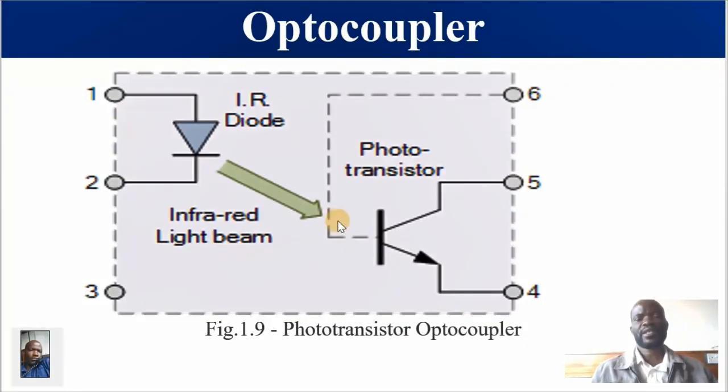That is a schematic diagram of an optocoupler, and as you can see, this is the housing. These are the legs, as you saw on that picture. It had 3 legs on one side and 6 legs in all. 1, 2, 3, 4, 5, 6. This is how the pins or the legs of an integrated circuit are numbered. You go down and then you go up.